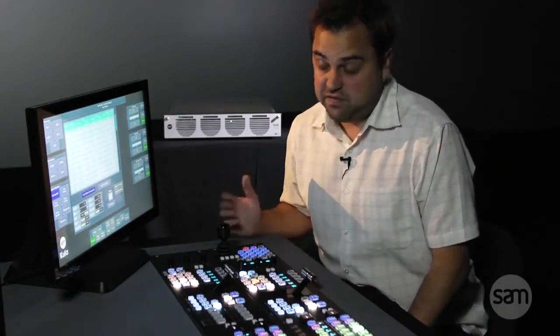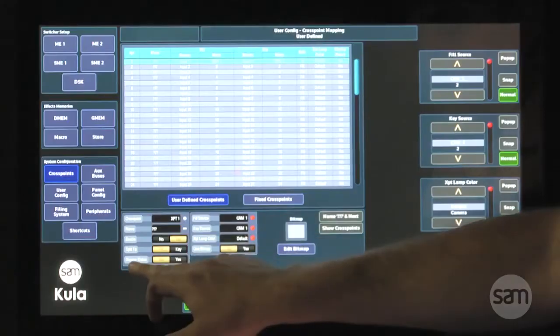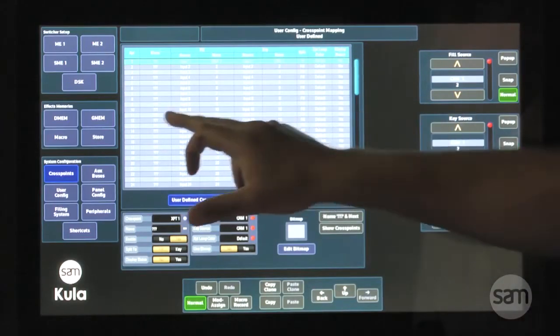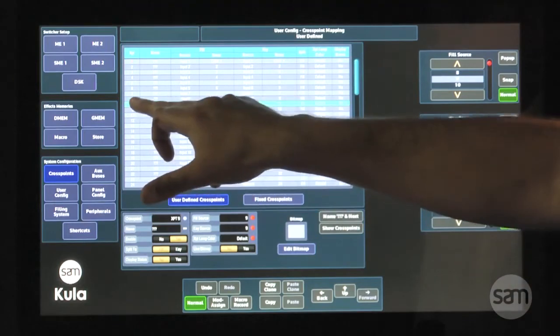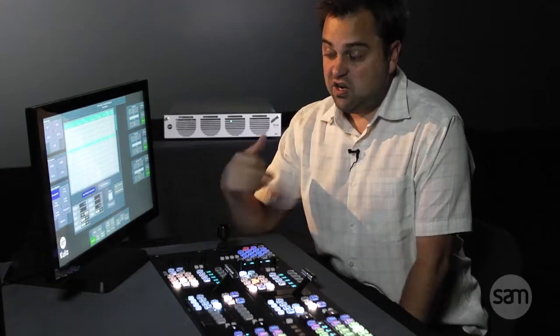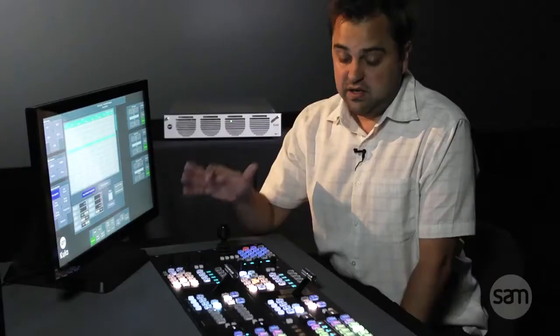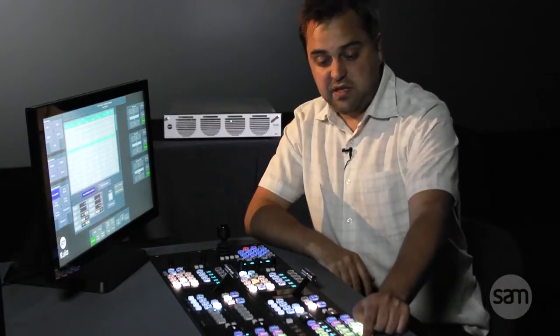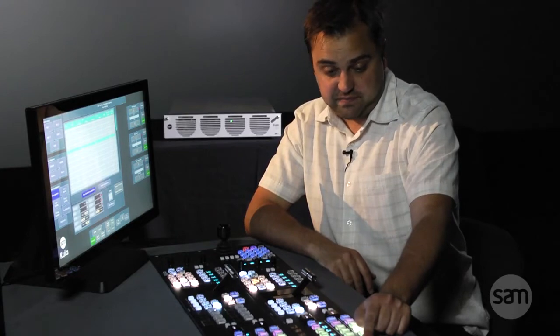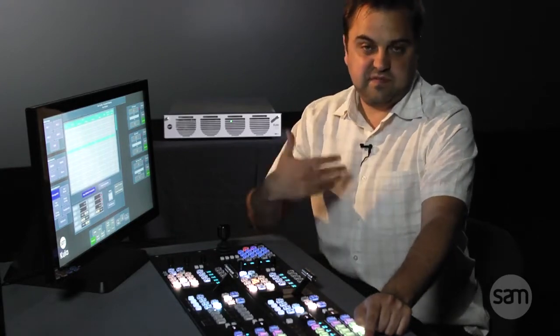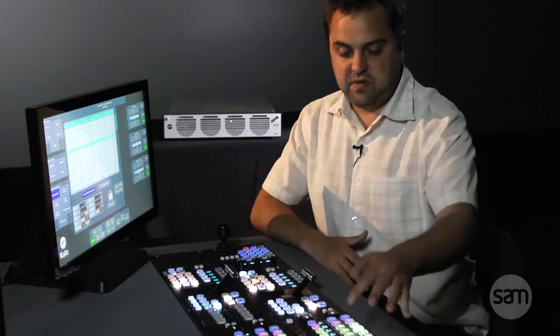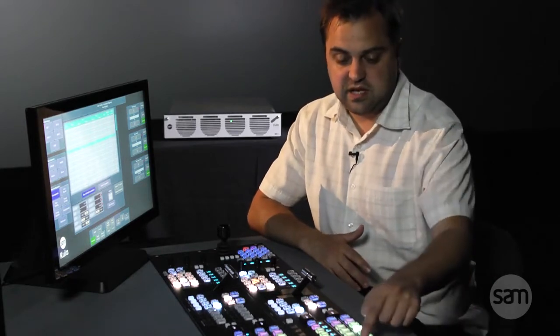Another handy feature for engineers, we feel, is a display status. Now I know, for example, crosspoint 9, input 9, I don't have any video on this. So if I put display status to yes, then on my input 9, it's giving me a message, no video. So a good way of coming to you, if you lose any video, then your users can tell you.